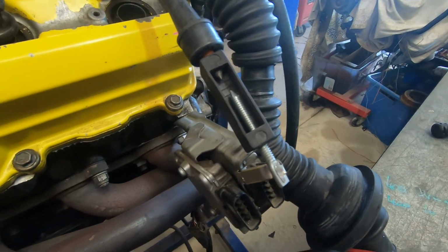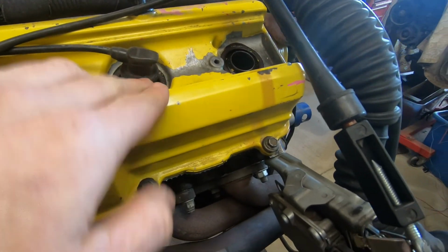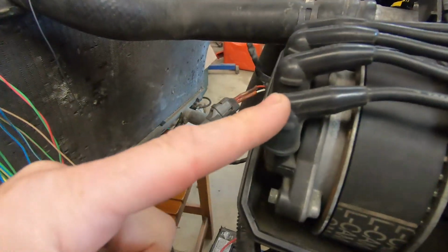How are we going to diagnose it? How can I show you what I'm talking about? And that gives me a little bit of trouble, because I want to check spark and I want to spray flammable liquid right by where I'm testing spark. And I've got 2 hands. I'm going to do it anyway. We might put some eye protection on. So I go straight over here to number 5 and number 7. The reason I go to number 5 and 7 is number 7 is off this distributor, and number 5 is off that one.